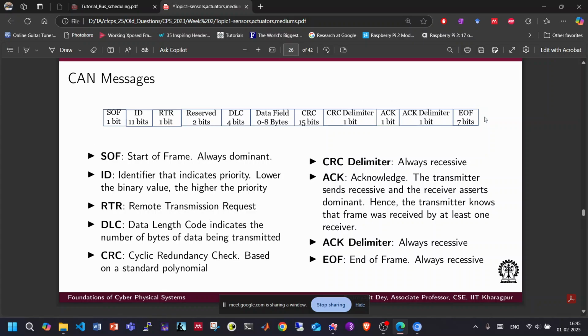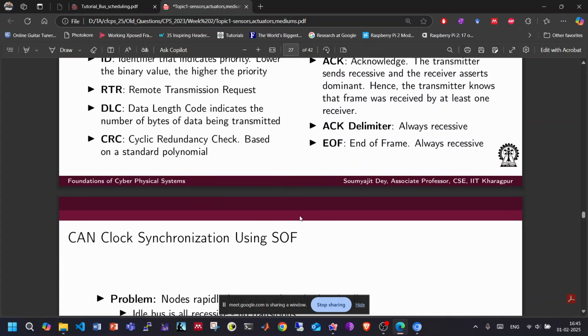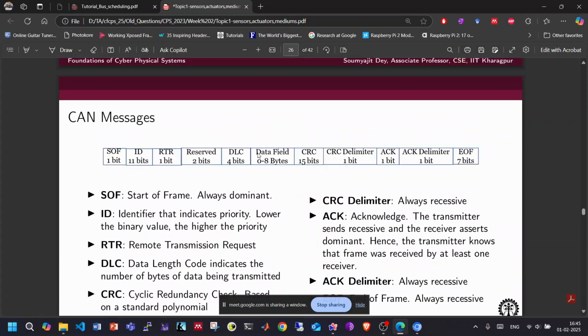So this is how a CAN frame looks like. These are the divisions in a CAN message. These are already written, so I am not going into this. Like we design any protocol, this protocol is designed like this, and the CAN transmitters understand the data, read the data from this data field. In the DLC field, this basically carries how long your data field will be, and in this data field there are 8 bytes of space which you can occupy and send data.